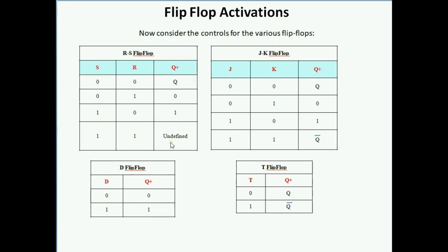That's why we call it undefined. And so we never want to allow both the R and S signals to become active at the same time, which is why the RS flip-flops are not really as much in use.